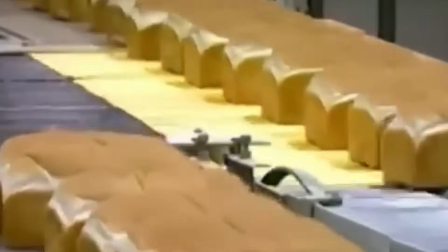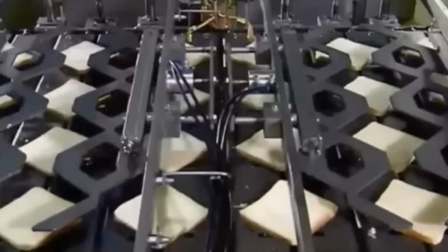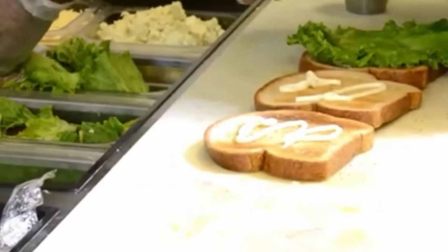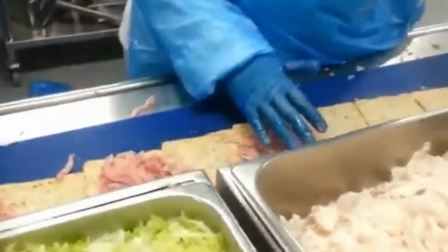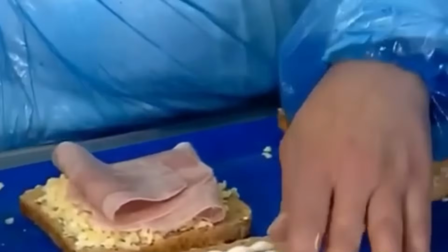The approved boxes move to the palletizing cell, where robotic arms stack them onto wooden or plastic pallets with layer patterns designed to balance weight and prevent shifting. The pallets are then rotated through a stretch wrapping station where film is applied under tension from bottom to top, stabilizing the entire load for transport. A final label is printed and applied to the side of the pallet with a scanner-readable code containing the production batch, shift, line number, and timestamp.